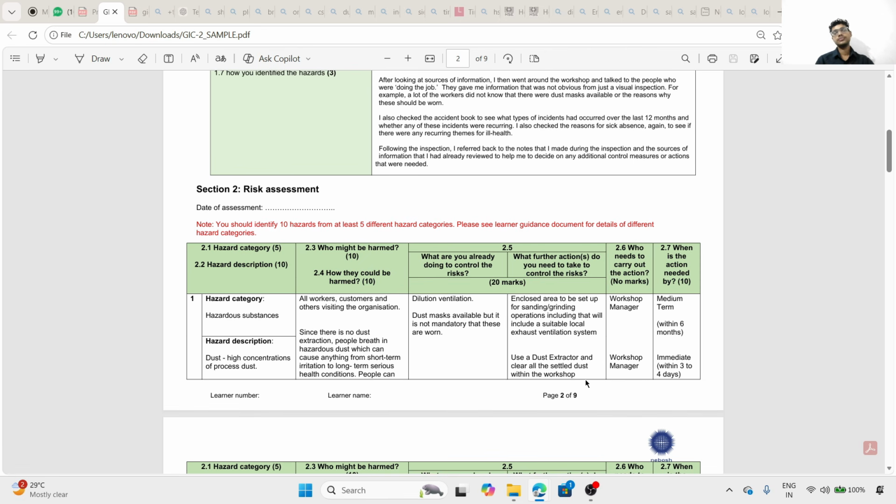So what we will do is discuss with the welder, the welding that you're doing at that particular height. It is becoming work at height, it is becoming dangerous, you're working at the outer section. The same welding you do on the ground, you complete that particular structure, and afterwards take the crane, and with the help of the crane you install it over there. So we eliminate, we substitute the risk. That is how the general hierarchy of control should go.